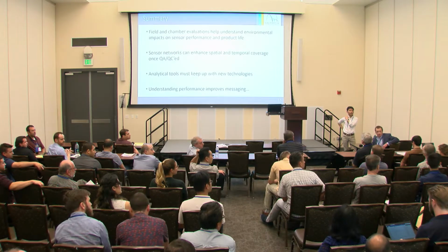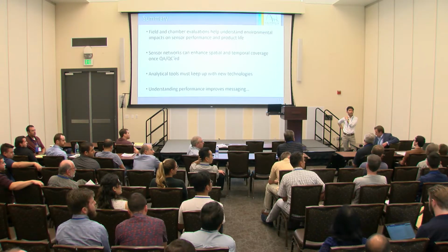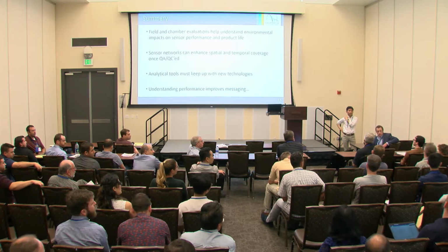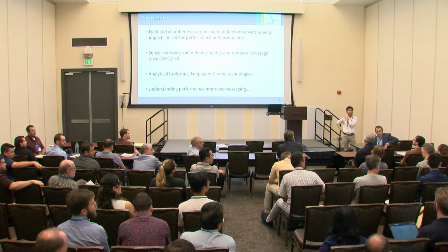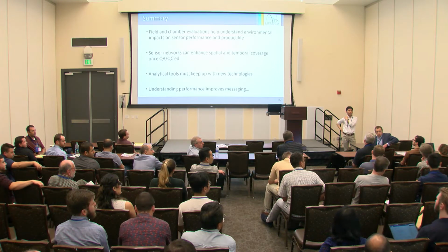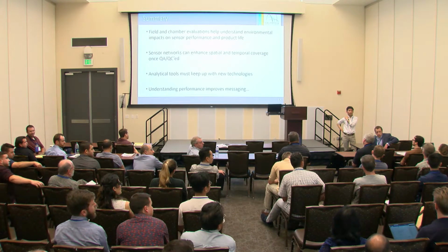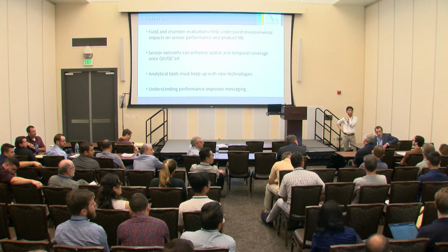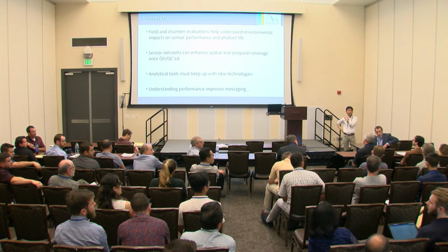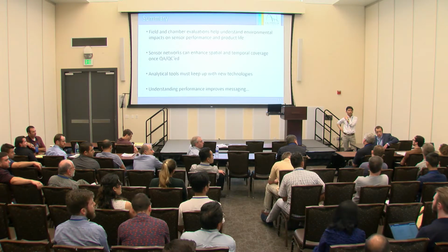So you guys use the BAM as the reference instrument to test all the sensors. I'm wondering if you have any thoughts on understanding bias associated with the measurement principle. The BAM is a much different principle than, say, the PurpleAir, which is an optical measurement. Even the BAM doesn't provide a full hour of measurement. So I was just curious if you've looked at teasing out differences in that bias that may be caused purely by differences in the measurement principle.